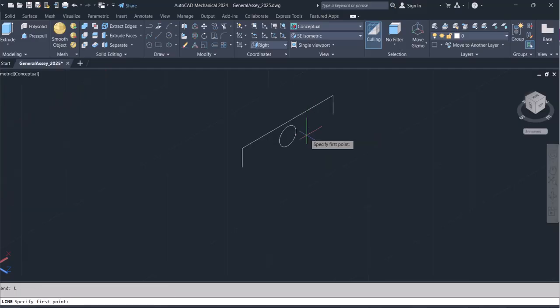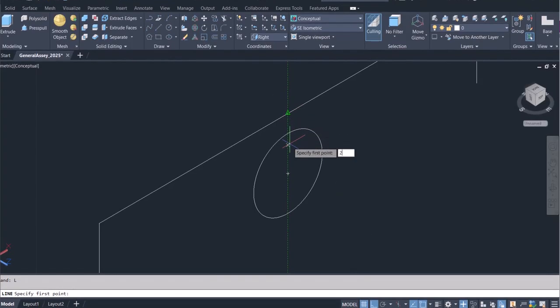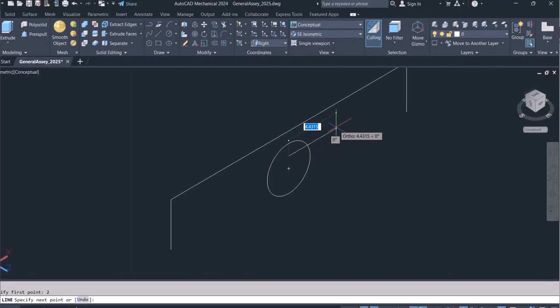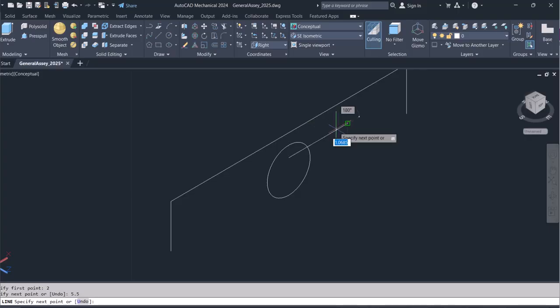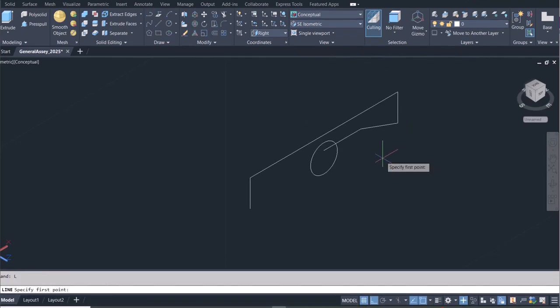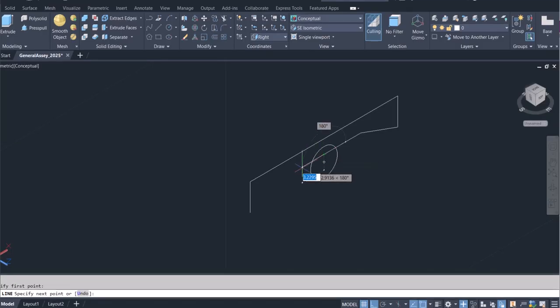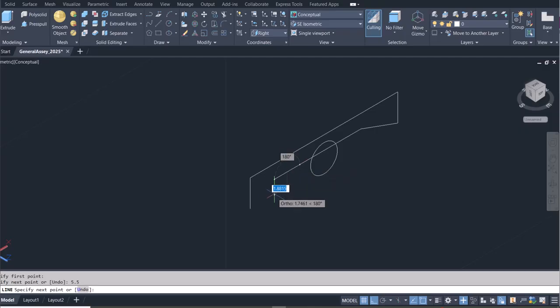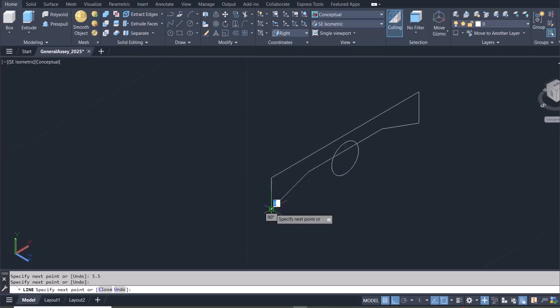So I'll now use a line. Now that line also would commence somewhere. I'll track a distance of 2 from here, so 2, and then this distance here should be 5.5, which is half of 11, and then I can connect this to that line. I can continue from here, so 5.5, and then connect this to that portion.